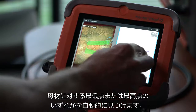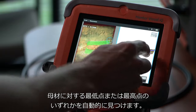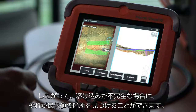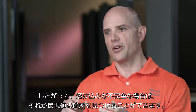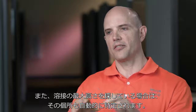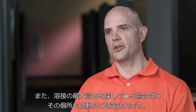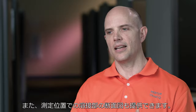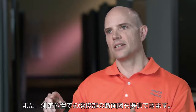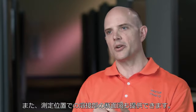And it will automatically find either the lowest point or the highest point relative to the base material. So if you have incomplete penetration, you can find the spot where that is at a minimum. And if you're looking for the maximum height of the weld, it will also identify that location automatically. And then it can provide an additional view showing a cross-section of the weld at the measurement location.